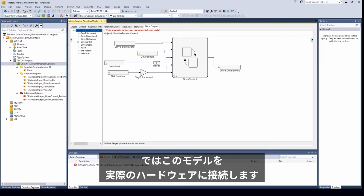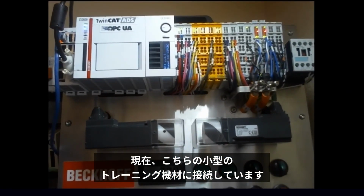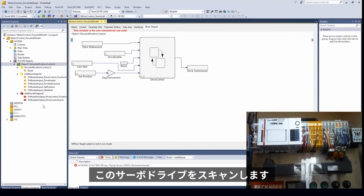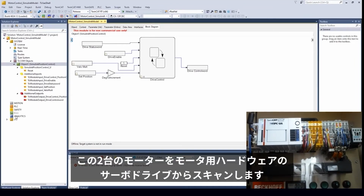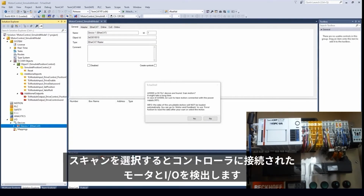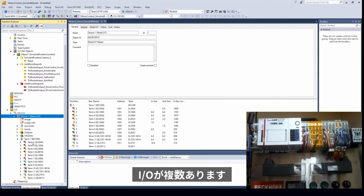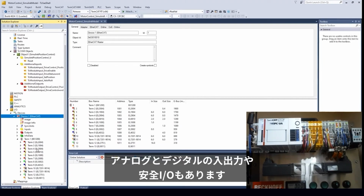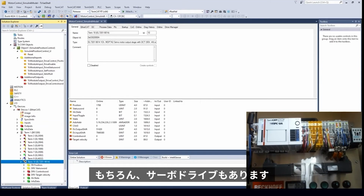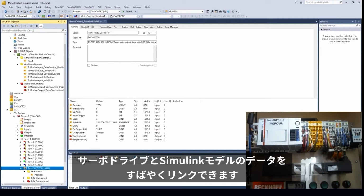And now, we'd like to link this model to actual hardware. I'm currently connected to a small machine here, or a training station, and what we'll do is scan in the servo drive. We see those two motors and we'll scan in the servo drive and motor hardware. So very simply, I can choose Scan and it will go find the motors and the I/Os that are attached to the controller. Now we can see multiple I/Os for inputs and outputs, for analog, digital, even safety. Here we see that we have a servo drive. Now we can very quickly link this data between the servo drive and our Simulink model.